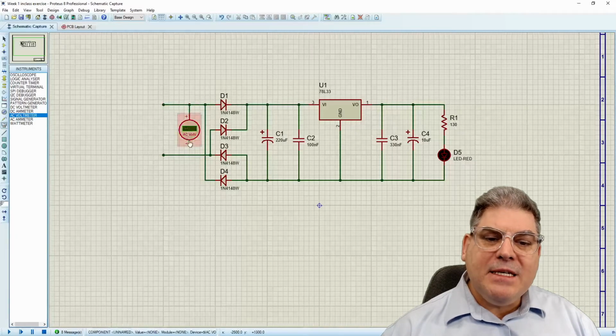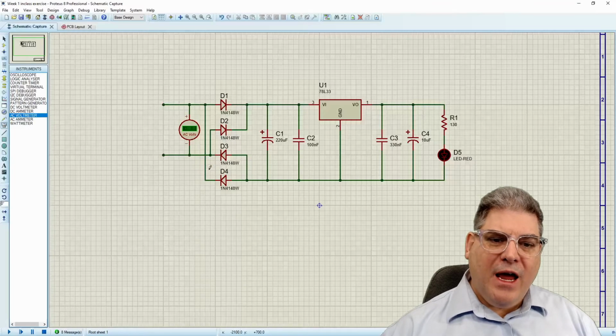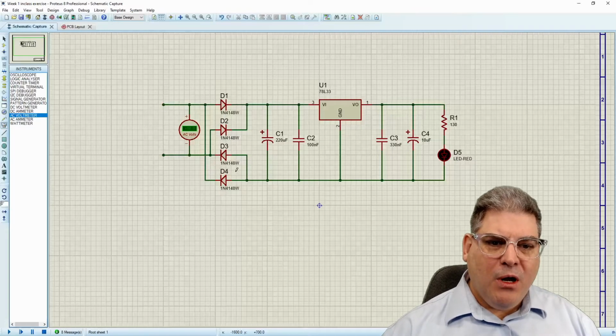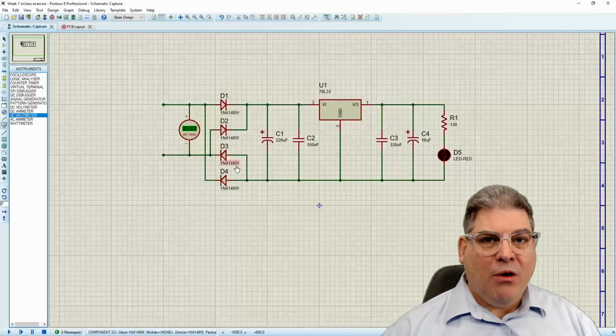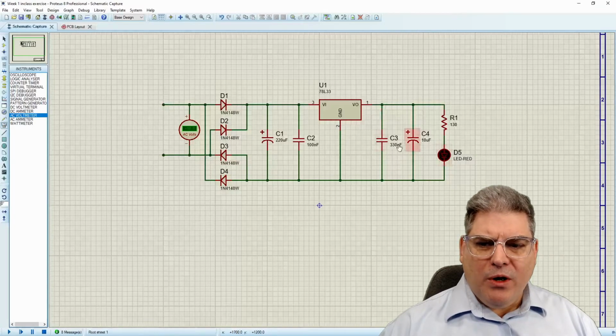If you put an AC meter on the DC side, you will only be measuring the alternating current component of the signal. So all of the DC gets filtered out, and vice versa. If you put a DC voltmeter on the AC signal, all you'll be measuring is the offset of voltage, okay, or the DC component.